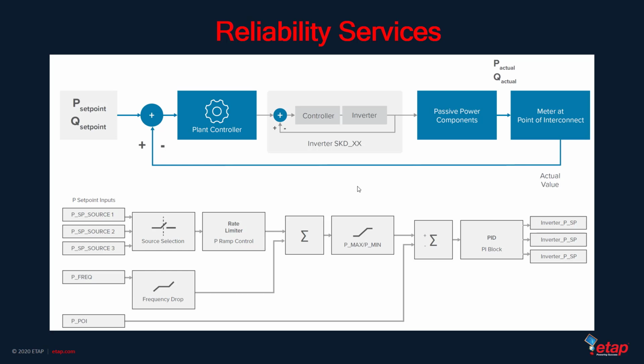And this is what is tricky and difficult to achieve in simulation mode. Discrepancies between the current set point and the instantaneous output at the point of interconnection manifest as an error which is used to correct the output. If the change in the set point is too extreme, the output will overshoot the set point before it has time to correct itself. To prevent operator-induced overshoot or transients from the set point, the velocity limiter transitions to the new set point gradually.